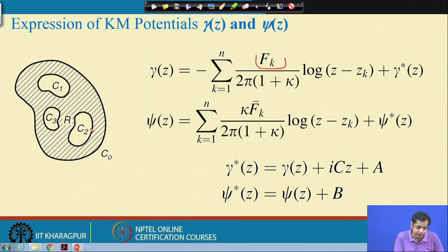For instance, in the given figure you have just three holes, so here k will be 1 to 3. And what is F_k? F_k is defined for each hole. If you have some boundary conditions, for instance, at this hole you have some forces specified, so we know the traction at the boundary, at this surface, at the internal loop. Now that traction can be converted into force.